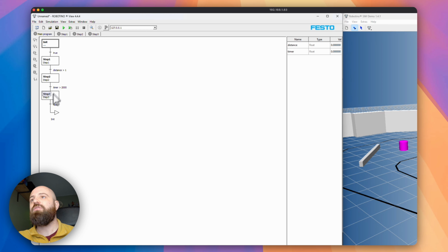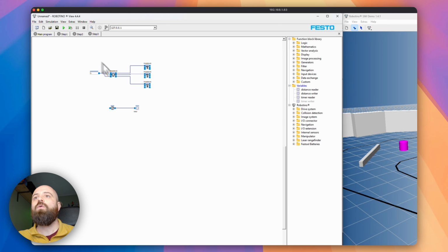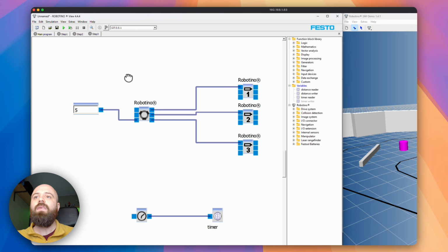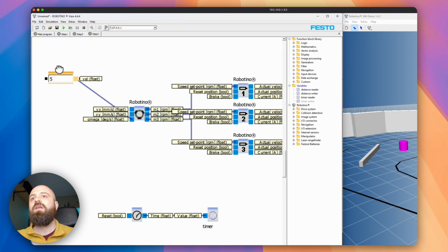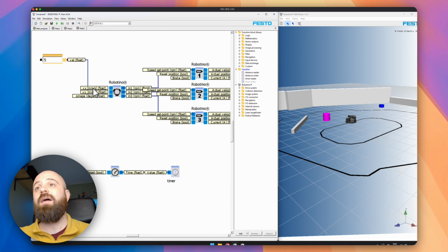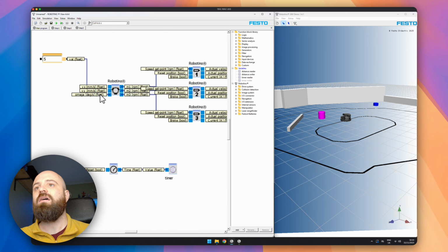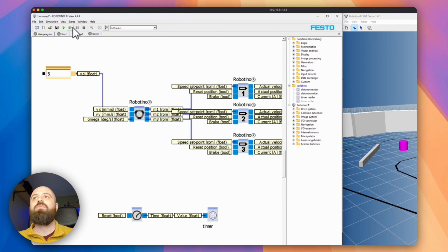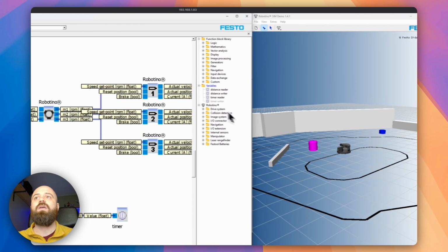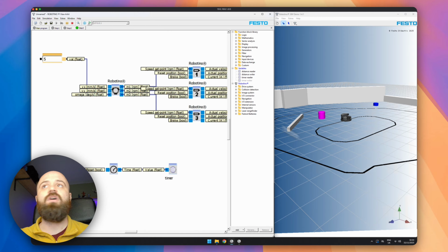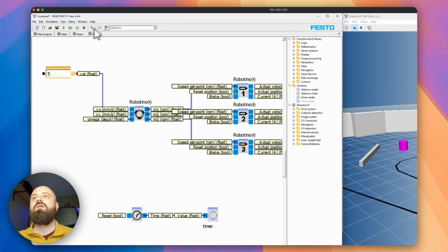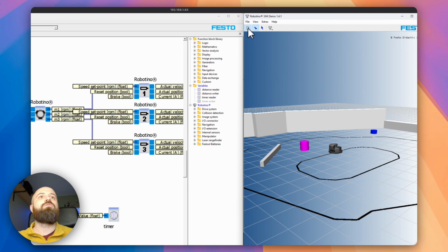And then in step 3, what have I done here? All I've done in step 3 is make it turn around. If I show the descriptions here, we looked earlier at this Robotino OmniDrive controller, we have X and Y, but we also have here Omega. This is causing it to rotate. If I just run this one step, step 3, and connect to the Robotino, there we go. We see that the Robotino is now rotating. So let me just reset that again.